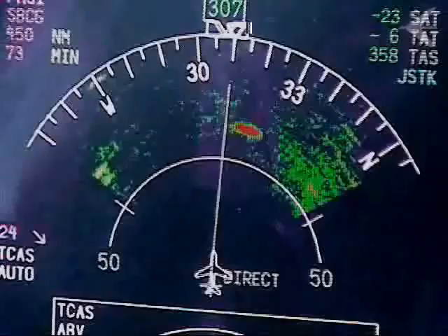Pinholes on the radome are caused by water bubbles under the first layer of its structure. These bubbles do not block the radar emission, but they partially obstruct the beam, as a dirty glass obstructs the light, resulting in significant radar signal attenuation.